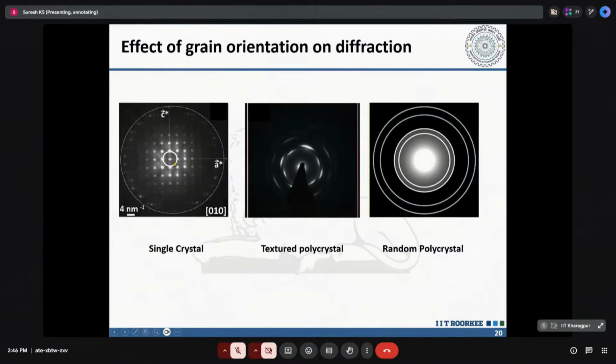peak. Again, depending upon the kind of plane which is having the preferred orientation, you may have only 2 broad peaks if the HKL plane is having a 2-fold symmetry, or you may have 4 broad peaks if the HKL plane is having a 4-fold symmetry, and so on. Whereas in the case of a randomly oriented polycrystalline material, in the phi rotation you may not observe any noticeable peak. The intensity will be almost flat as if we are traveling around this particular. It is equivalent to that.